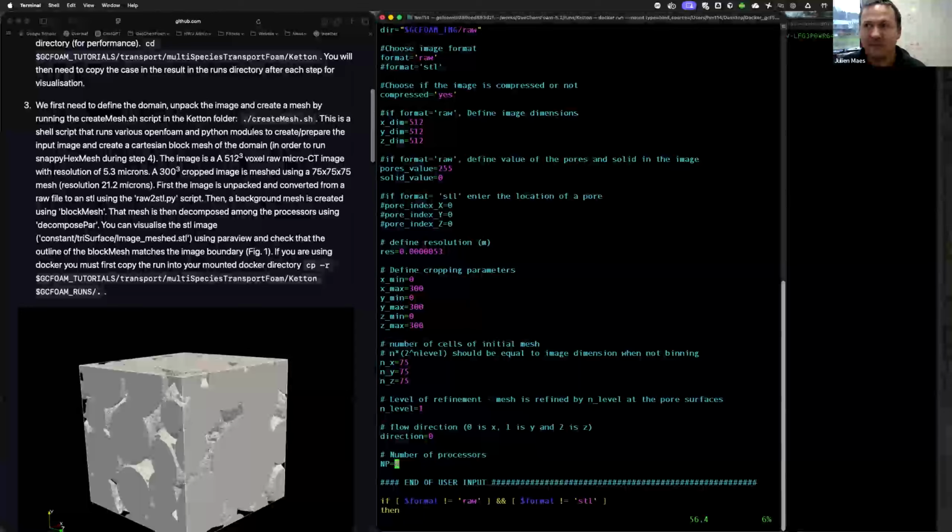Right, so you have a mesh that is 75, 75, then it becomes finer. You still have everything, right? And when the refinement has happened, you will then remove all the cells that are in the solid. Right, so if, for example, you're doing n level equal 2 here, so you get to the level of the resolution, the surface area of your STL is the correct one. It has not been downscaled at all. Okay. Yeah. All right.